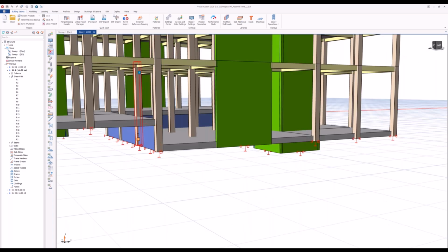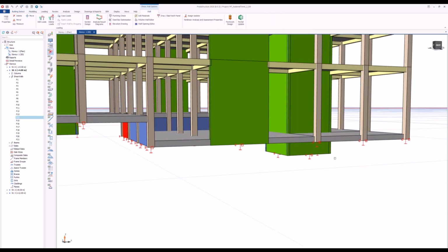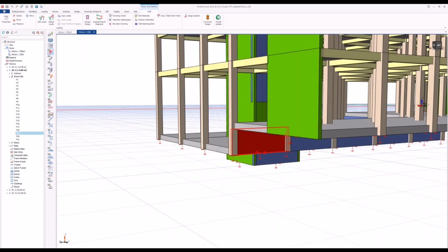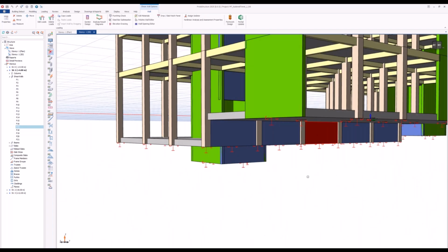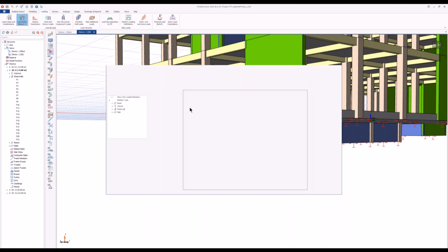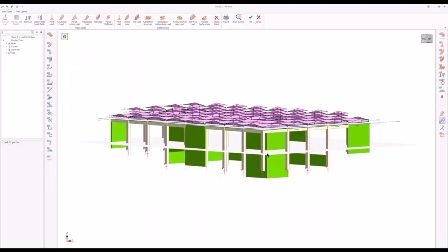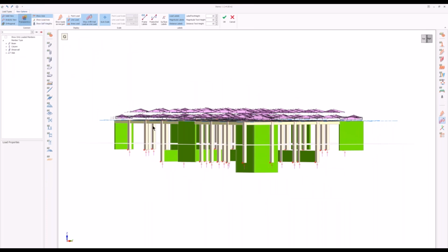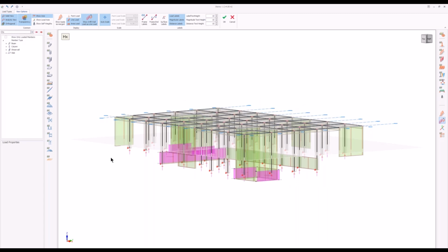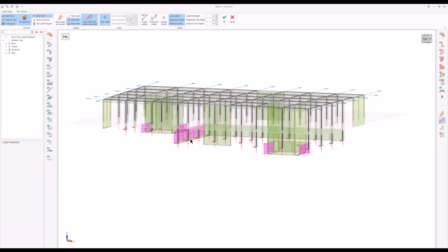for example, these walls, this one here, only this portion, will be supporting the soil. We have to define some soil loads on these walls. So how to do that? Of course we have the load editor here. Let's open the transparency to see it better, and change the load case to HX load case, which is the soil load in X direction.